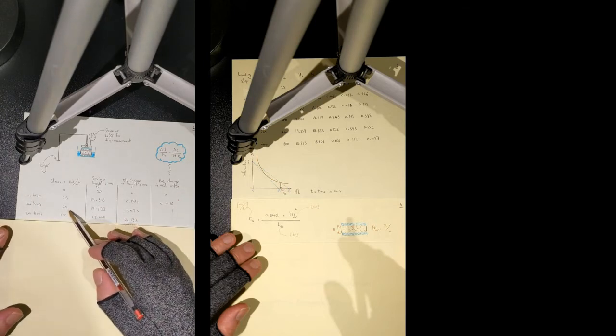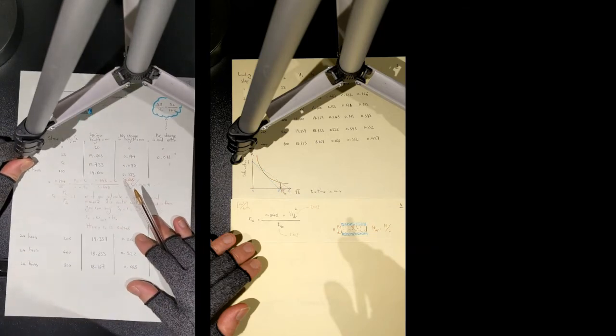Same, this will take 24 hours. You go to the second set, doubling up the load from 50 kPa to 100 kPa and redo the test, repeat the test. And in fact, you can do this as many times as you need.